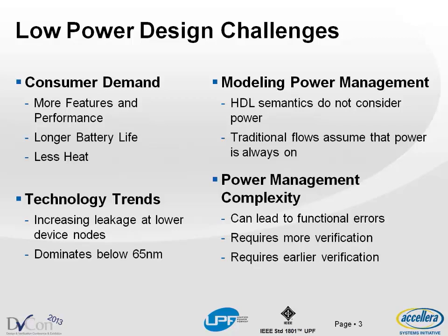Modeling what goes on with power management is also a difficulty in that the hardware description languages that we use traditionally don't understand power. They don't model the effects of power. Hardware description languages have always assumed that power is on when you start, and it stays on throughout. So modeling the effects of power management is something that we have to add in on top of what hardware description languages usually do. And of course, power management adds complexity to the design. So that leads to more potential for functional errors, more requirements for verification, and a need to do verification earlier in the process.